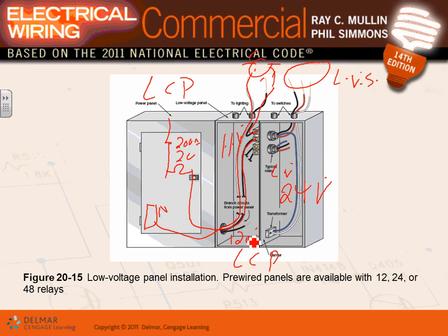That's a code requirement. The relay panels that you can get, guys, they can get them in 12 relays, 24 relays, and 48 relays, and you probably can get them in different arrangements too. So the panel that you guys came up with, I don't know how many, do you remember, Derek, how many relays you came up with when you were filling them? Maybe 20. So you're going to go 12, 24, 48, basically. So the actual size, we don't care. We keep filling it. And when you submit it with your project, guys, the manufacturer will provide you with this amount. If not standard, it'll give you the next standard. Any comments, guys? Any questions about the lighting control panel?